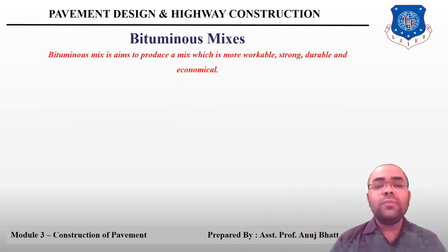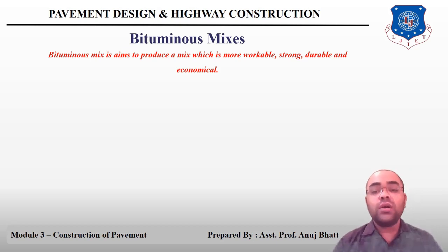Why are we providing a bituminous mix? Generally, bituminous material has binder property, and to enhance that property with more workability, more strength, more durability, and also to make that material very economical, we prepare a bituminous mix. A bituminous mix aims to produce a mix which is more workable, strong, durable, and economical.